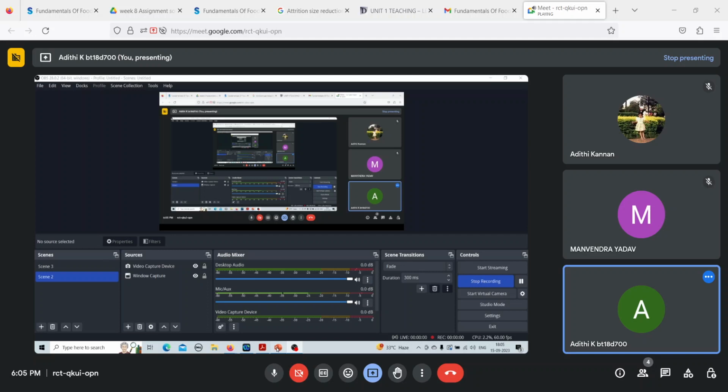Now this is just the critical speed, but the rotational speed is maintained at 70% of the critical speed. That is your operating speed. So the operating speed is equal to 0.7 into Nc, substituting the value of Nc that we calculated, that is 0.7 into 35.1 rpm, which gives me 24.6 revolutions per minute.